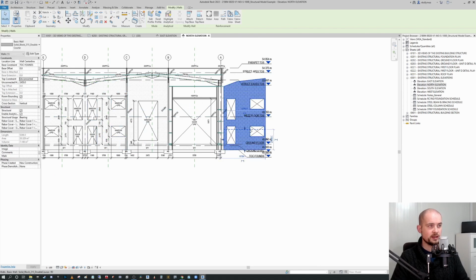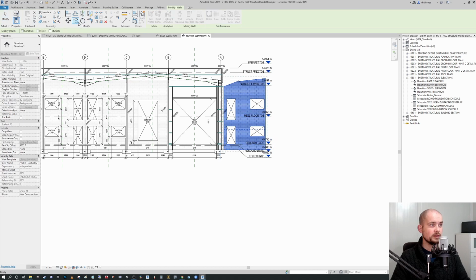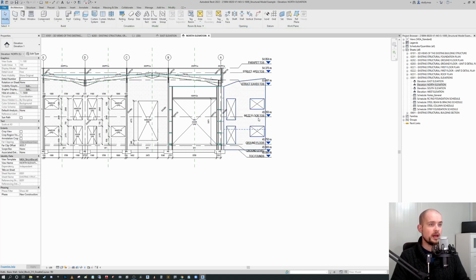So let's say I did that, okay? And then I went to use the copy tool again. You can see that constrain is kept, but multiple was turned off, okay? So constrain is kept as a standard because it is a wall and therefore it should be locked into plane. But you can see that the multiple, which was selected previously and I turned off, is now turned off as a default and will be remembered as turned off the next time I turn on the program, okay?